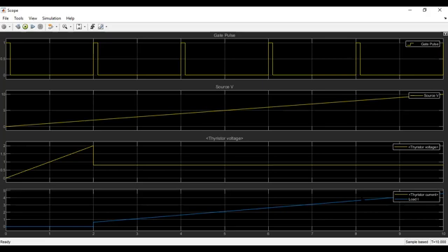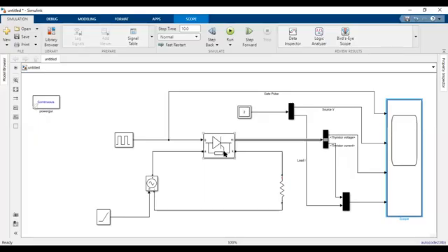We cannot see the yellow line. The reason for that is, if you see the circuit, the output current, the load current, is equal to the thyristor current. Let me share you the circuit again. This is the circuit. See the cathode current, IK, is equal to the load current. The input current is the summation of anode current and gate current. IA plus IG is equal to IK. So the total input current is equal to the cathode current, the current getting out of the cathode,